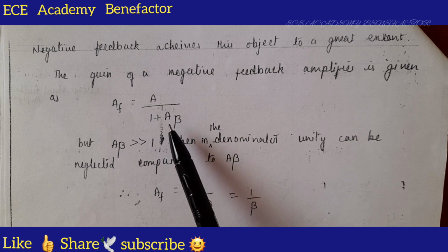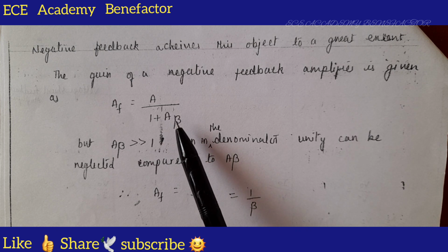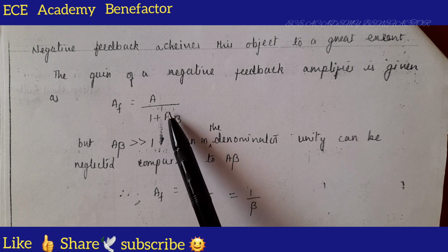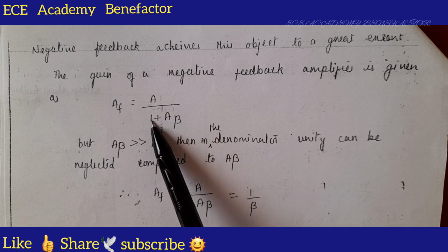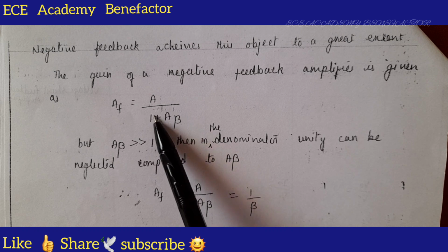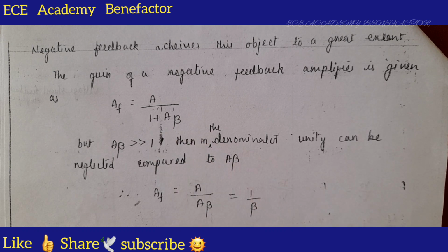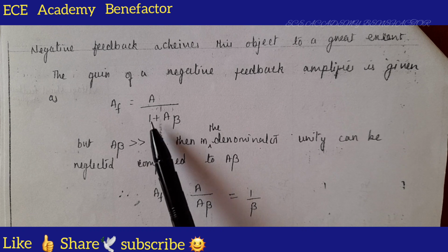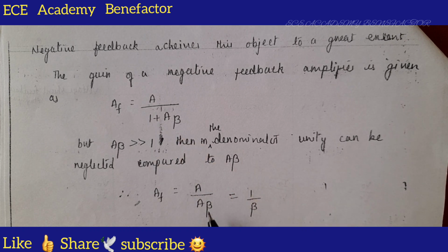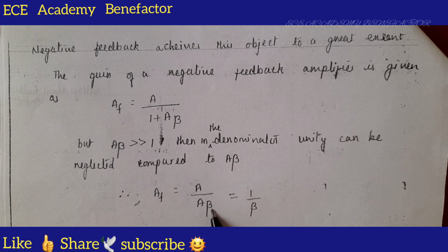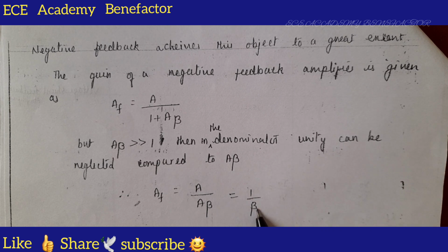So how can we make the gain stable? One way of doing it is, if we make this A beta value very large compared to 1, what will happen? A beta is large, so 1 becomes negligible. So we can write this equation, if 1 is negligible, this 1 is negated. So this AF equation now becomes A by A beta. A gets cancelled and it is equal to 1 by beta.